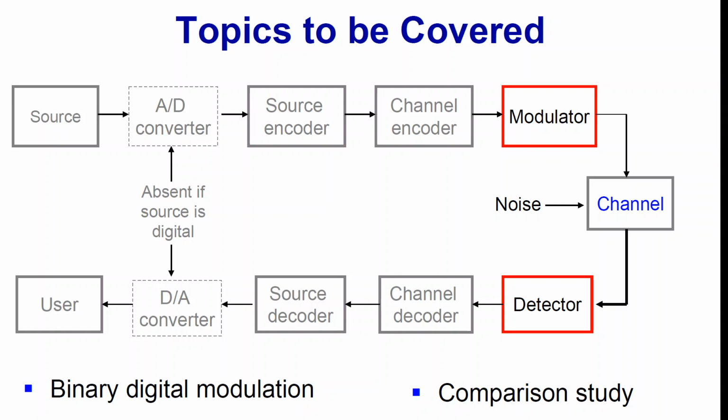In baseband pulse transmission, a data string represented in the form of a discrete PAM signal is transmitted directly over a channel. So it is the pulses. First, the binary signal is converted. You remember b_k was the binary symbols, zeros and ones.